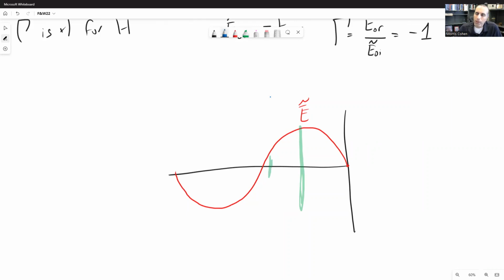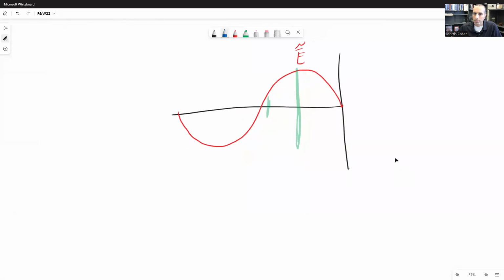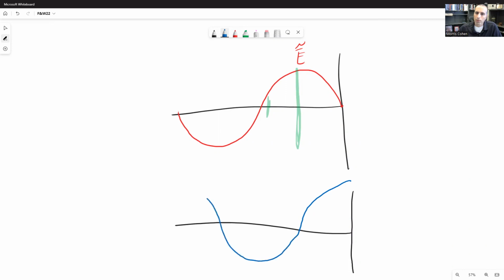All right, the magnetic field will be a little bit different. And let me just draw that side by side here. Magnetic field will be a little bit different because that reflection coefficient is positive 1. And so at the load, we actually get a doubling of the magnetic field. So the magnetic field will look like this. It's going to start out very high, and it's going to crash down to 0. And then it's going to proceed like this and continue on.